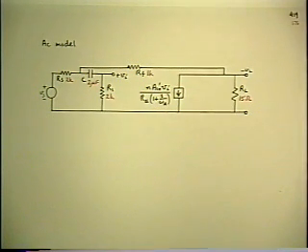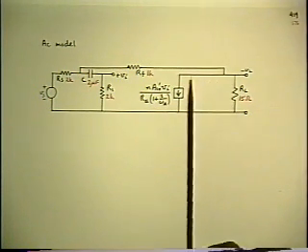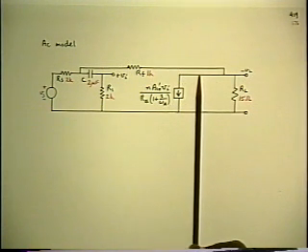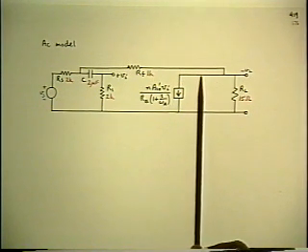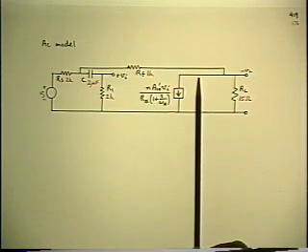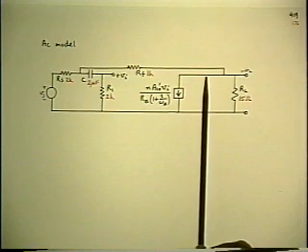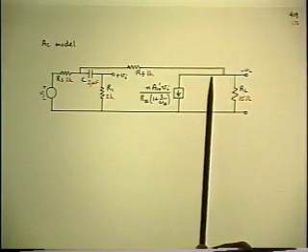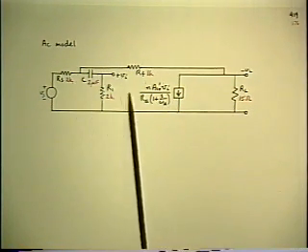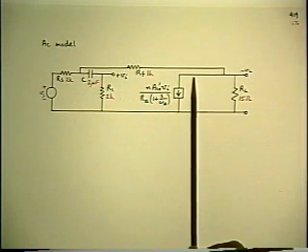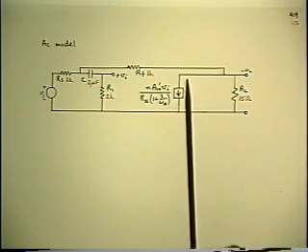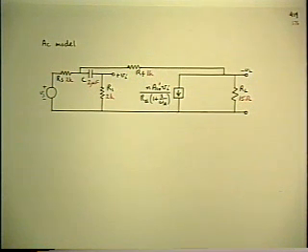What we've done so far is choose the point at the output of the final current generator to inject a test current in parallel for the purpose of calculating the loop gain. This sets up a current Ix that goes forward, and we followed it around the loop all the way back to the current generator, which is equivalent to the Iy, which comes back to the same point. And we've done the analysis for that using the extra element theorem as a shortcut along the way.